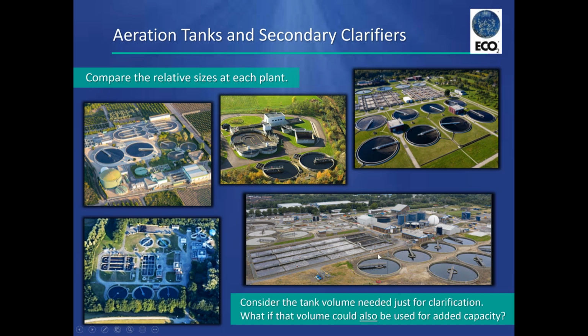So to minimize the electricity consumption in the aeration tank, we would look at that and say, we keep the dissolved oxygen very low, normally less than 2 milligrams per liter. And if we keep that dissolved oxygen at 2 milligrams per liter, we satisfy the aerobic metabolism.